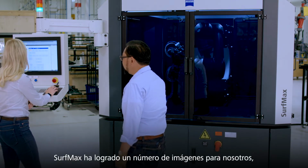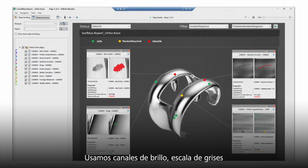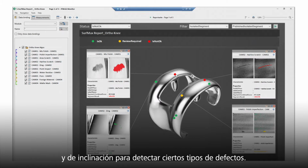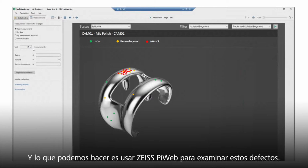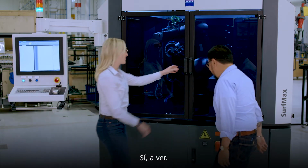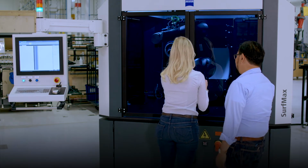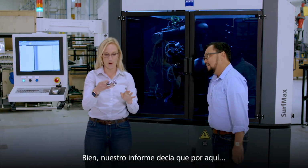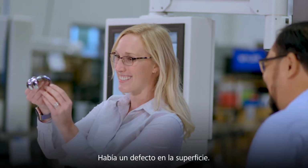Okay. So the SurfMax has acquired a number of images for us, and we can analyze these images on a number of different channels. So we use gloss, grayscale, and slope channels of information to detect certain types of defects. Got it. And what we're able to do is use PyWeb to look at these defects. So shall we take a look at the part? Yeah, let's see it. All right, so on our report, we could see about here, there was a defect on the surface there.